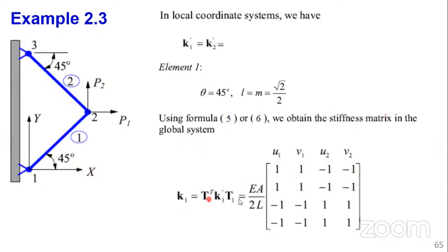So using that formula, you get EA over L. So of course, for element 1, when theta is 45, for these angles, 45, 60 and 30, you can utilize special triangles to simplify your working. You can also start punching the calculator, but you should be smart. As engineers, you should be smart. Where you find something that is unique, and you know that we have a short way or a short form of executing that, then you should go ahead and utilize it.